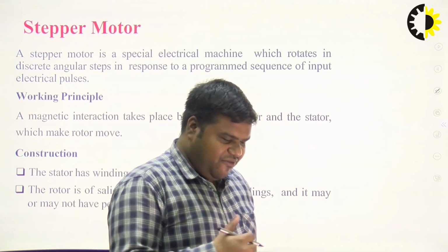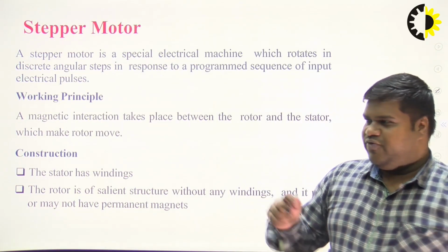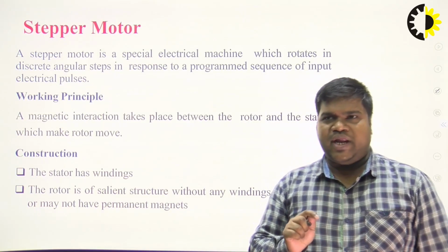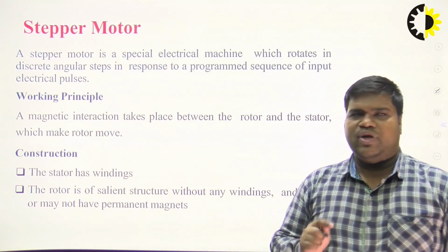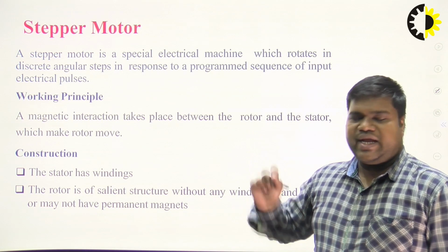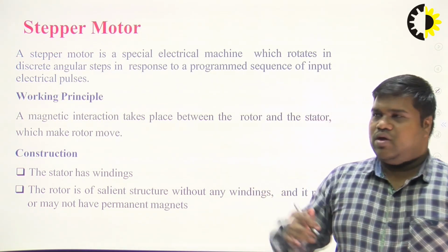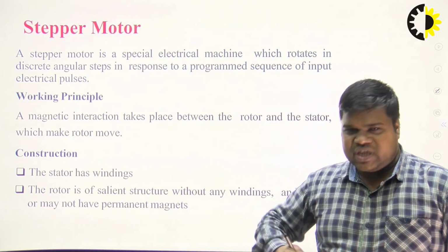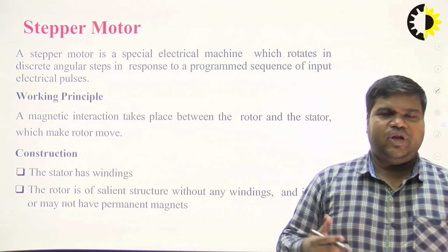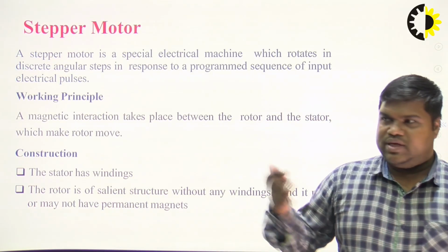So when I would wish to rotate the rotor at an angle of 15 degrees, the suitable motor to consider is the stepper motor. The stepper motor works on the principle of rotary motion as a result of the excitation of triggering pulses.